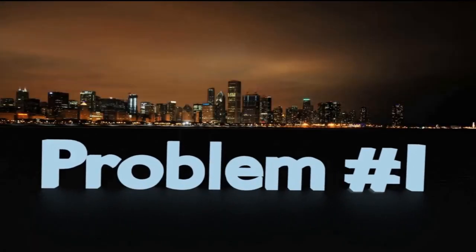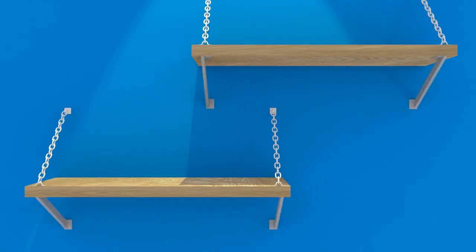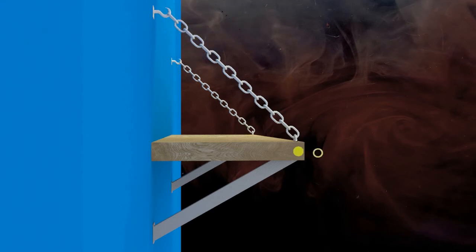Let's have a look at the first example. Suppose a shelf is attached to the wall. One side of the shelf is rigidly secured to the wall, but the other side is not, which may lead to bending or even fracture of the shelf once it is full of objects. So to support this free side, chains are provided which will pull the shelf in upward direction, and brackets are provided to withstand the load. And we want to find out the magnitude of reaction forces acting on supports at point O to maintain the equilibrium of the assembly.